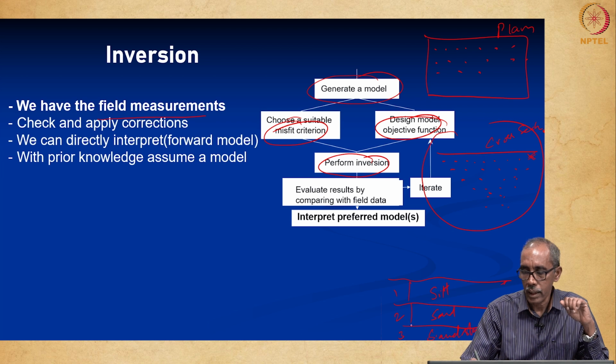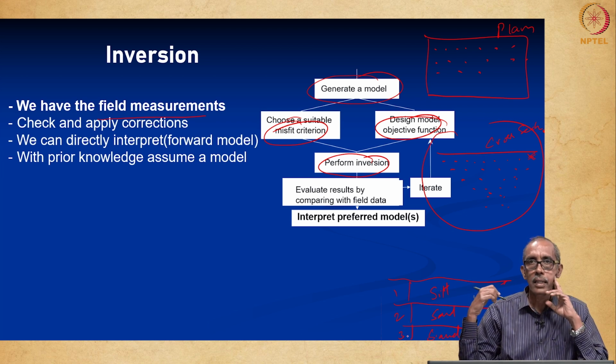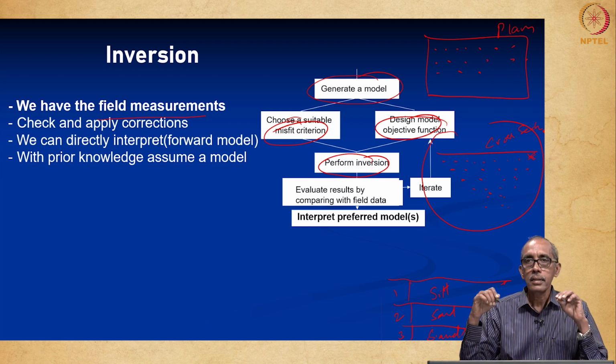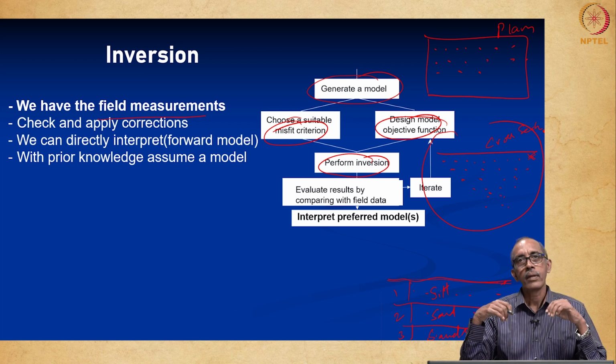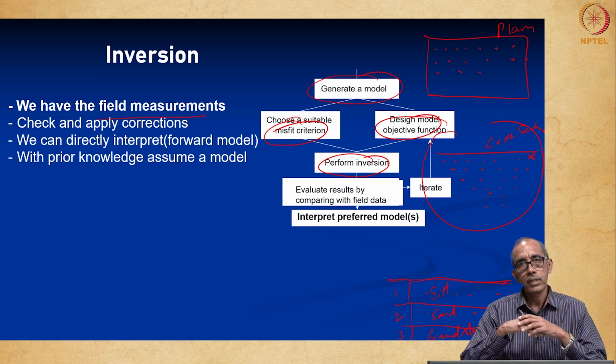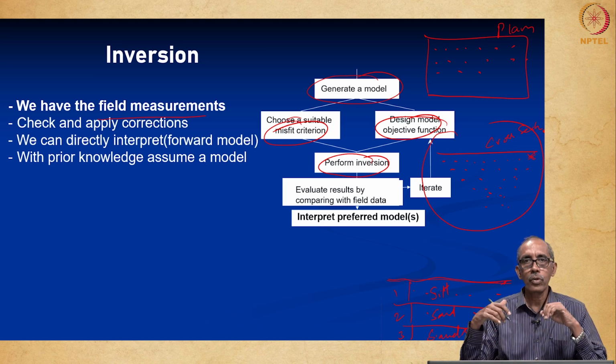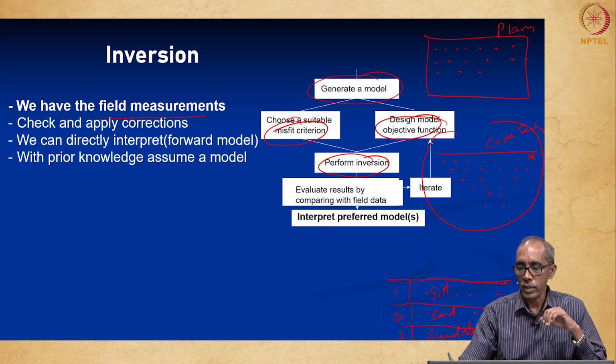We assume certain thicknesses for these layers, and in such a situation, if you carry out the investigation on the surface, the value which we will get can be theoretically computed. What is the induced polarization which we will get for these assumed formations of certain thickness, some true resistivity?